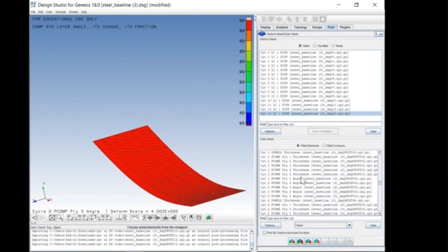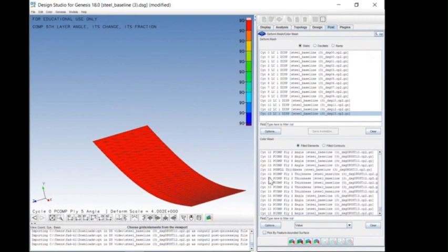Okay, by the time I get to design cycle 13, I scroll down to design cycle 13, my layer 1 thickness is now 0.000252 millimeters. Layer 2 is 0.00847 millimeters, and so on. Layer 3 is 3 mil, which is the maximum, which is what we do expect.